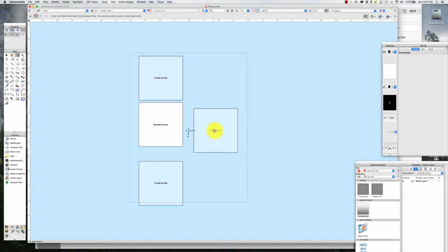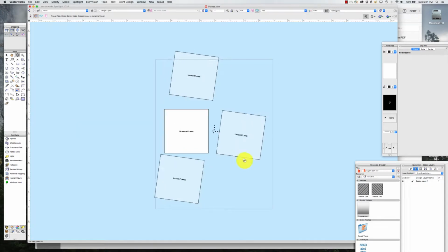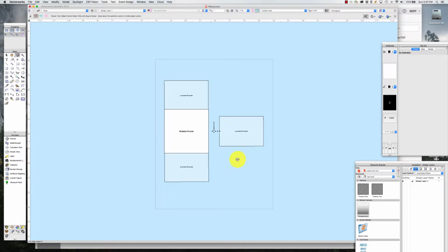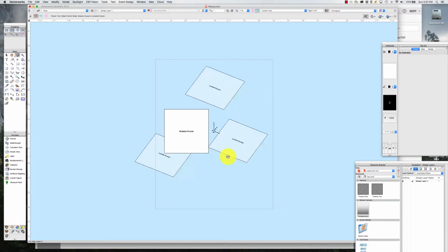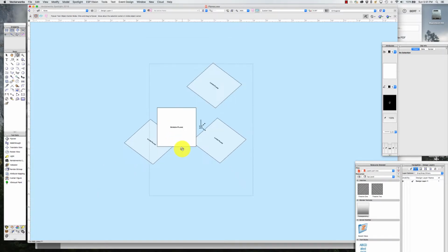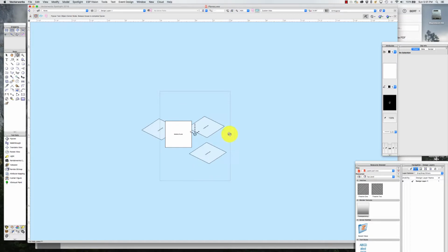So if I go into 3D mode, here's what's happening. You notice the screen plane does not move. It's as if it is actually drawn on the screen. I can zoom in and zoom out and it will get bigger or smaller, but other than that, no matter what view I go into, whether through rotating or through using one of the custom views. So you'll see now that the objects that were drawn in layer plane, since they're just squares from the side, just look like lines.